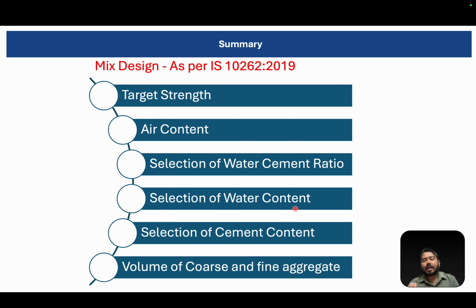Okay. So for that reason, as I said, you need to calculate the workability value, and based on that workability, whether you need to add excess water, you are going to add it. For that you can use the codal provision that for every 25 mm extra slump, you have to add 3% of water. And again, you have to subtract the superplasticizer. If your normal superplasticizer is there, it has a water retention of 23%. If you are designing a high strength concrete, then the water retention will be 30%.